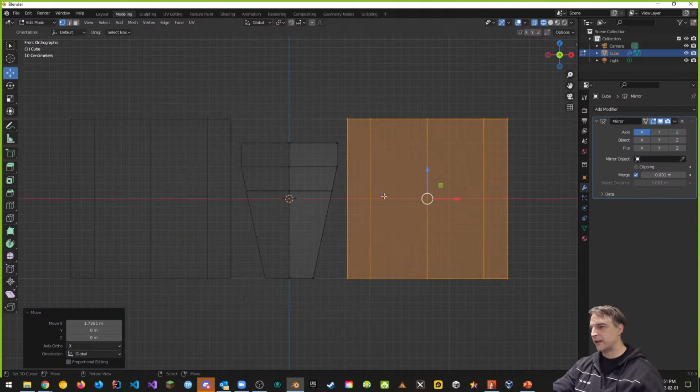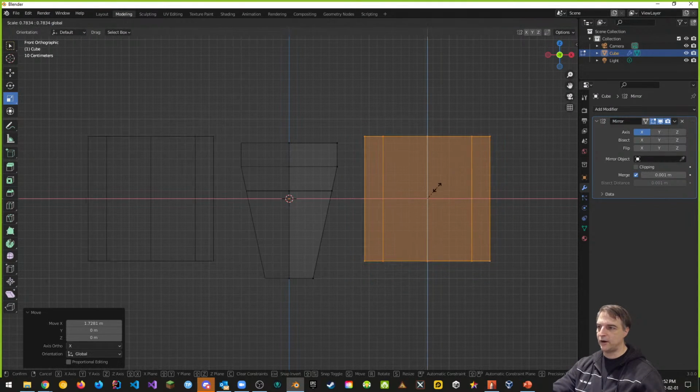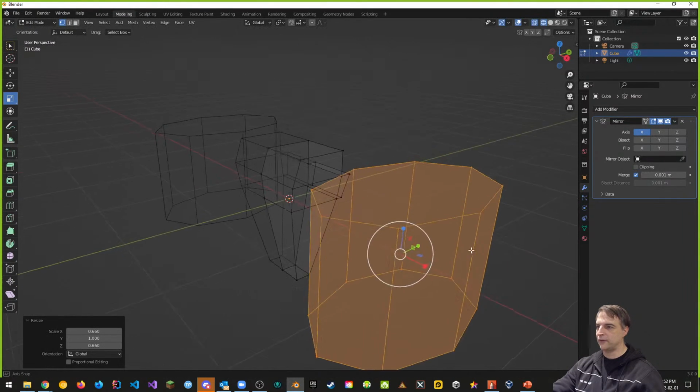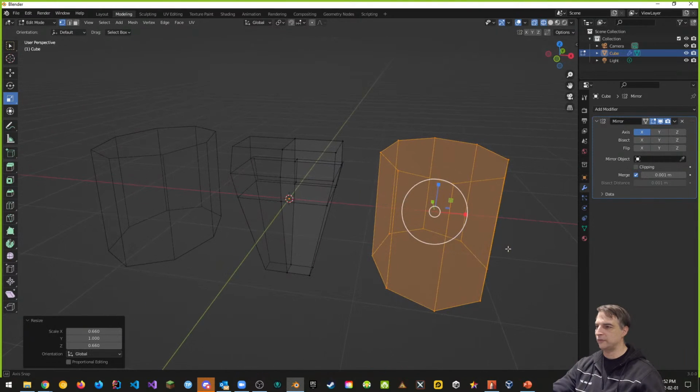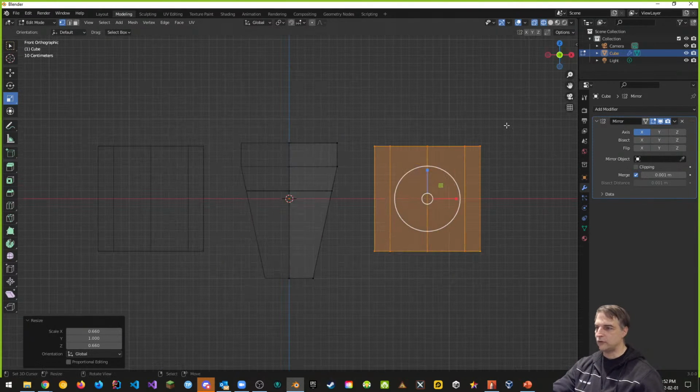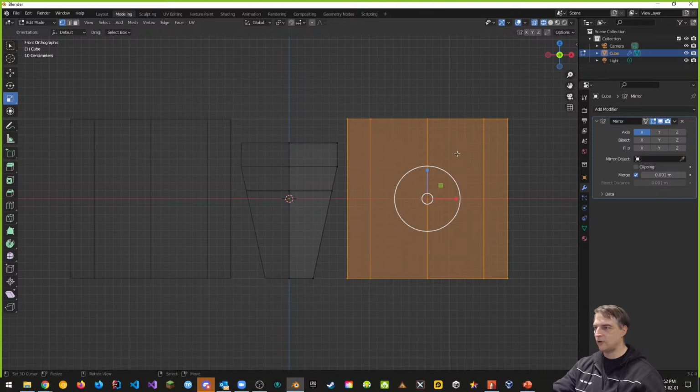What I want to do is scale this down a lot. So I want to press the S key, or you can use the scale tool, this one here. There's a couple of ways. If you use this little green square, you'll stretch it both ways. But be careful, on the side it doesn't do it, it only does it from the front. We'll have to do it on the side as well. So let's undo that and go back to this.